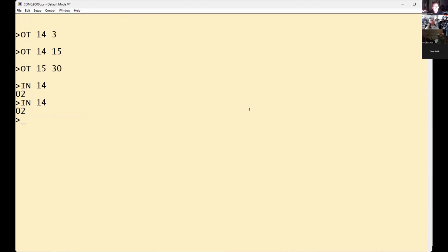Like I said, what I would do is rip out the 2SIO JP and make this port 0 and port 1, just on 10 and 12. And then see if it'll boot CP/M and your console works, and see if you can talk to your modem on the second port without the 2SIO JP in there. Well, I'm going to disconnect this other one. I disconnected that jumper from the Altair to this thing because that's also on 20.